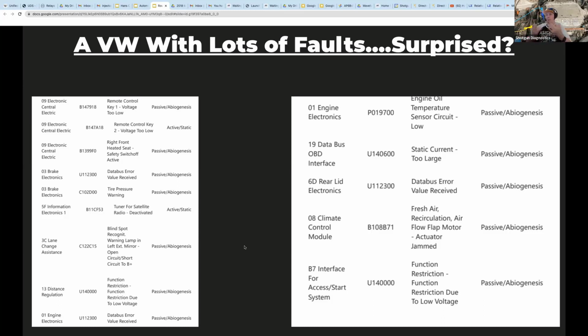And that one is designed more for the heavier duty operations. Now, there are still some brand new BMWs that will draw more than 90 amps during a programming event. So you need to be aware of what vehicles you're working on and find out the maximum amperage they're going to draw when they do this, and make sure you get a power supply that's going to do the job, right? And the TopDon may not meet the needs. You might need something higher powered.